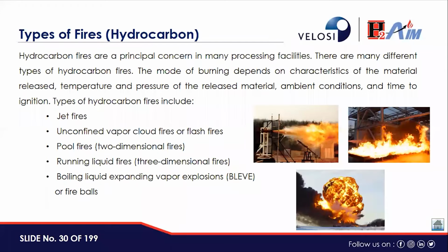These are the different types of fires, and I should also mention hydrocarbon fires. Hydrocarbon fires are a principal concern in many processing facilities. There are many different types of hydrocarbon fires, like jet fires, unconfined vapor cloud fires or flash fires, pool fires, which are two-dimensional fires as well. Then running liquid fires, which are also known as three-dimensional fires, and then boiling liquid expanding vapor explosions or fireballs.